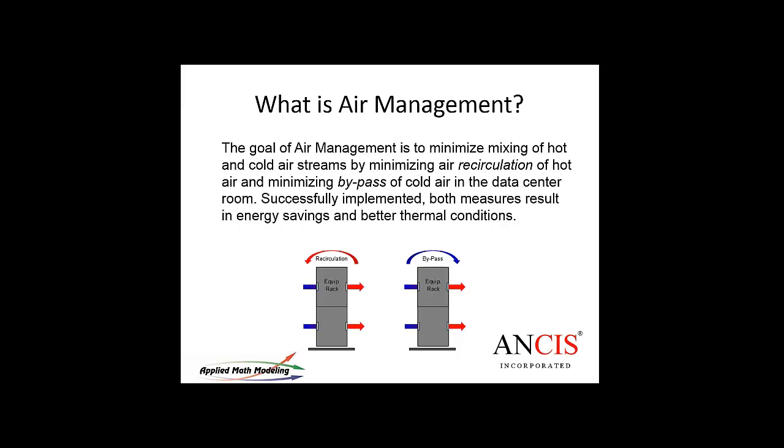So Magnus, this is a lot of your input here. Would you like to just take us through the next couple of slides on air management? Yeah, this slide tries to explain what air management is all about, and essentially it's about avoiding recirculation, and that's what they show on the left-hand side. That's when hot air is coming back over the racks or around the racks to the air intakes, and that's when you get hot spots that can knock out server equipment over time, or actually at the moment too.